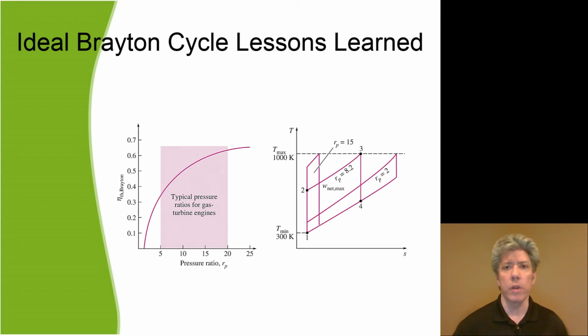And so the stronger the engine has to be. And typically what that means is that's so much more metal that you have to add just to provide that strength. Now, if you start making a very heavy Brayton cycle engine, you're going to quickly end up with an engine that won't lift a helicopter off the ground because the engine's just too heavy. So the highest pressure ratio for the highest thermal efficiency is not necessarily the best idea.